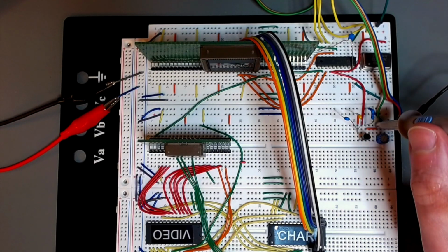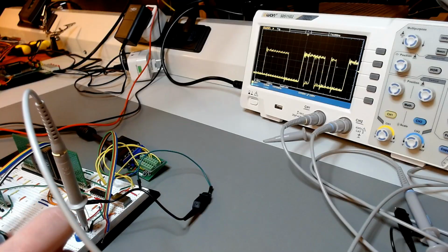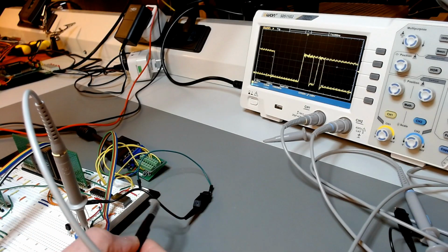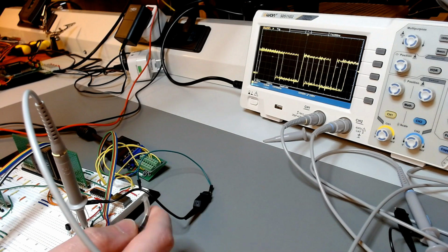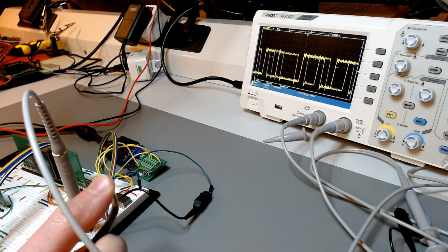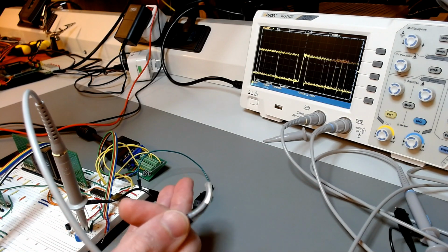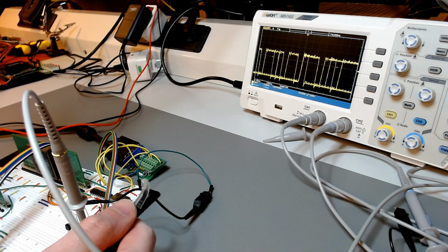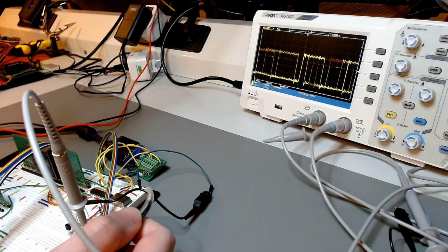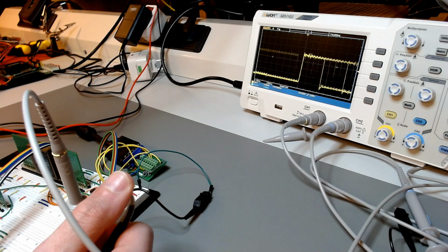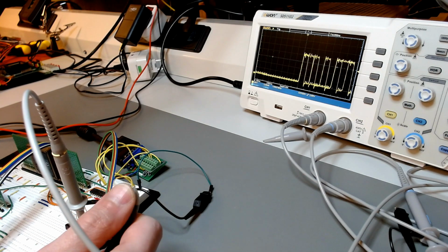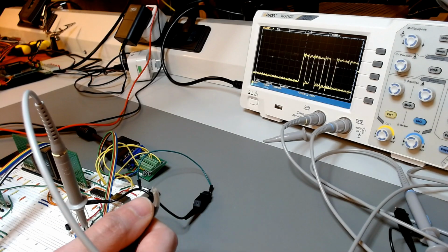Now in principle, for a regular VGA monitor, 4 volts is more than enough. A regular VGA monitor expects a peak-to-peak amplitude of only 0.7 volts. So why am I trying to get even more than 4 volts? Because for some reason my TV, which also has a VGA input, seems to expect TTL level signals, so a peak-to-peak of 5 volts. But these 4 volts will do.